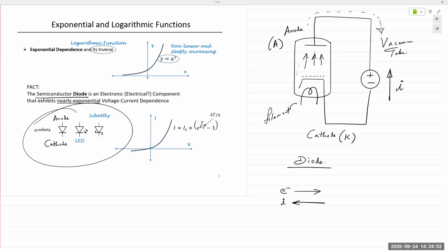Now, if you look at the lab kit and you have a regular diode, or any kind of diode for that matter, the most typical packaging for the 1N4000 series is a black opaque epoxy package. And there is a cylindrical band running around that package. It's grayish silver. That band indicates that terminal is the cathode.